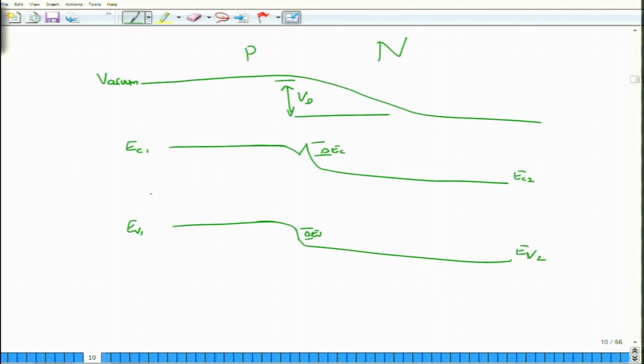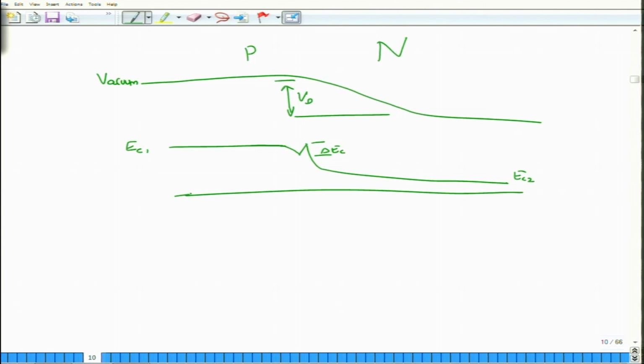Again in the equilibrium position, let me move it, because in the equilibrium position the Fermi level has to be closer to N, but it has to be closer to this material also, right. So, you will actually have EV1 here. So, this is the Fermi level which is constant under equilibrium, drops down, there is a sudden drop of delta EV and then drops down to EV2 here. Okay. So, this is what the band diagram of a small p and a capital N region would look like.